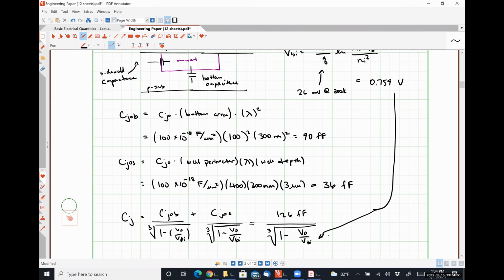You can actually use those masks to make features on a wafer that are much smaller by using oils and stuff like that that have a different index of refraction, so that effectively the pattern that's projected onto the wafer surface itself is smaller than the physical patterns that you've laid out, right? So going from one size to another is usually some sort of technique like that, where it doesn't require a large change in the equipment or anything like that.